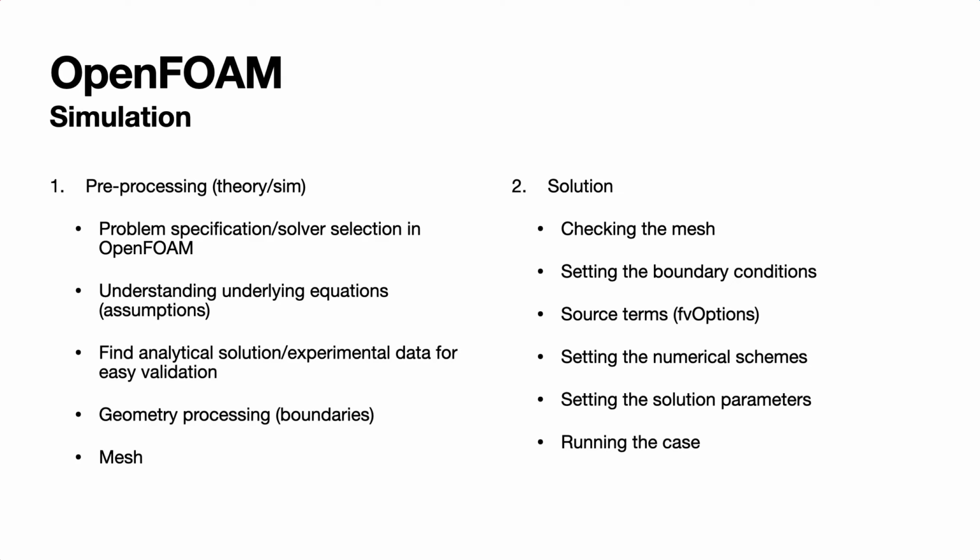For OpenFOAM, there are some steps that we follow. First of all, we need some pre-processing in terms of defining the problem and selecting a specific solver in OpenFOAM. We'll have to look and check whether the equations that are there are the ones that we need to solve. And it is always a good idea to find some experimental data or analytical solution so that we can compare our results and validate our numerical setup.